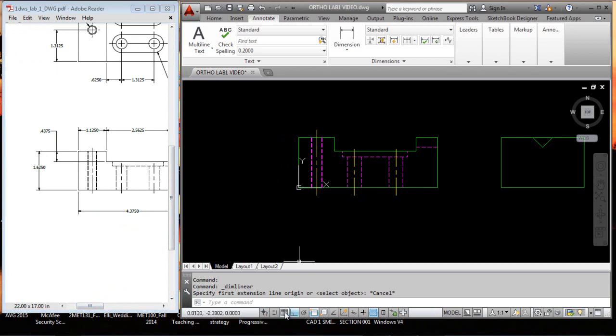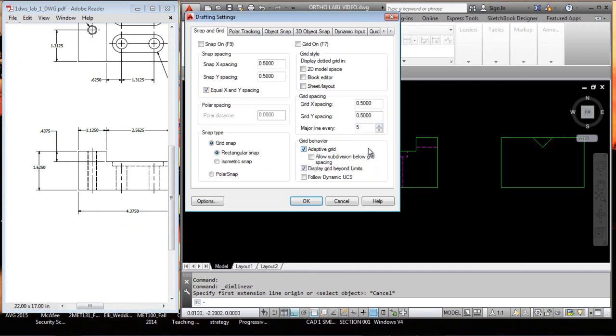So we can go here to the grid, and you can right click and hit settings, and here's the snap. Okay, now note the snap is set at a 1/2 inch by default, and we really want to set that snap at 375. That's 3/8 of an inch. If you set the snap on the x-axis, and click onto the y, then it will follow suit.